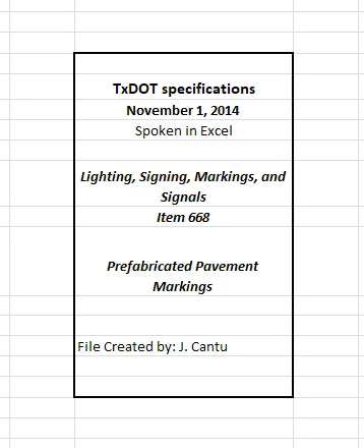3.5 Surface preparation. Prepare surface by any approved cleaning method that effectively removes contaminants, loose materials, and conditions deleterious to proper adhesion. Abrasive or water blast cleaning is not required unless shown on the plans. Blast clean, when required, in accordance with Item 678, pavement surface preparation for markings.